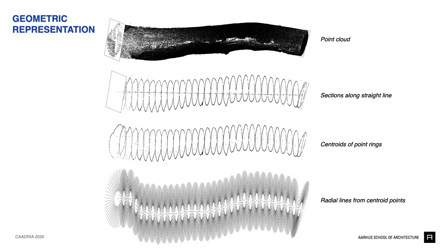The point cloud from the scanning of the saw log is processed with the Volvox plugin and custom scripts for Grasshopper in Rhino. The main task is to define a center curve, since this is used for the selection and placement of logs. The end planes found from the scanning sets the overall direction.